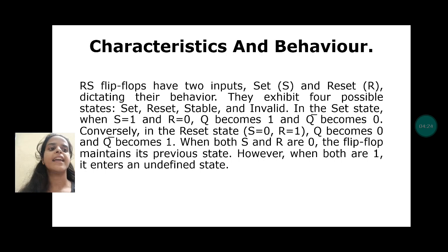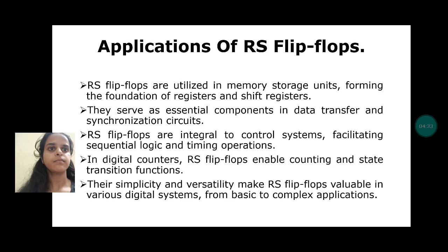When both S and R are 0, the flip-flop maintains its previous state. However, when both are 1, it is an undefined state. And these are the applications of RS flip-flops. RS flip-flops are utilized in memory storage units, forming the foundation of registers and shift registers. They serve as essential components in data transfer and synchronization circuits. RS flip-flops are integral to control systems, facilitating sequential logic and timing operations.